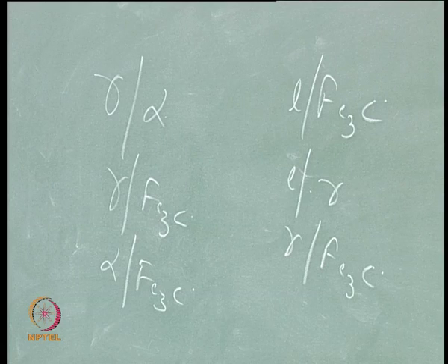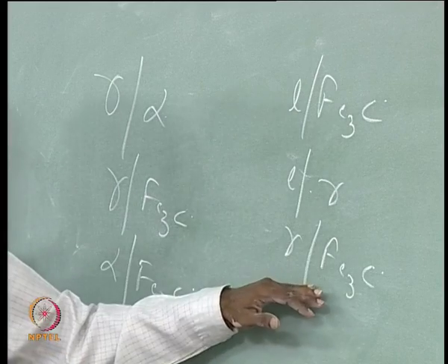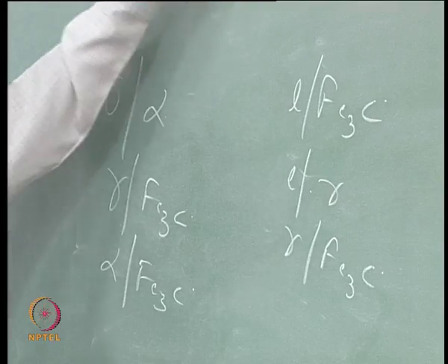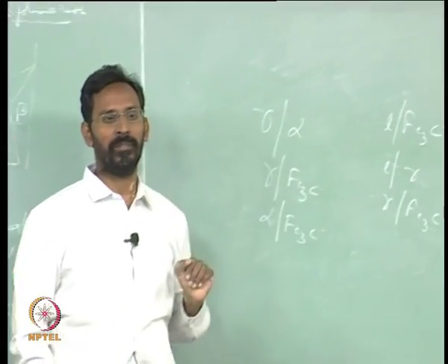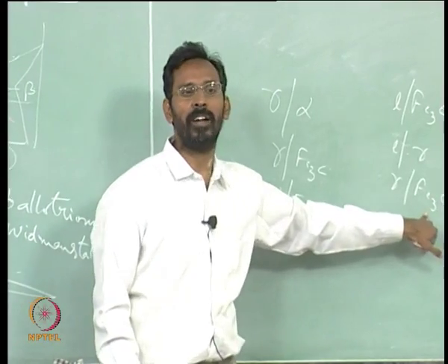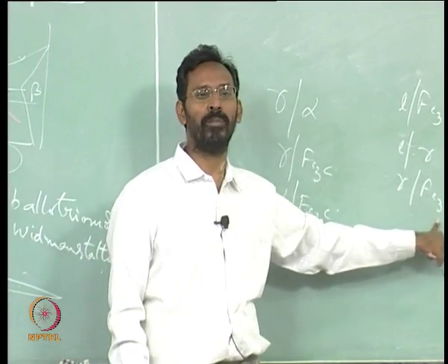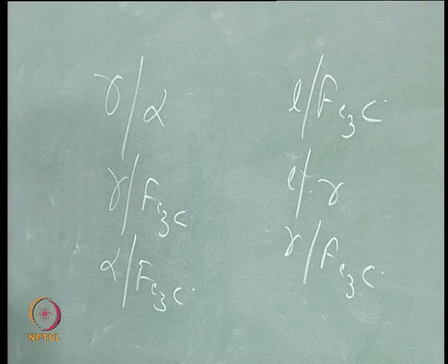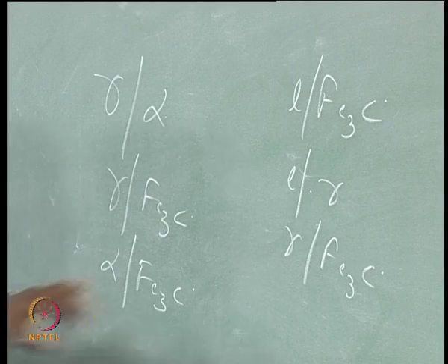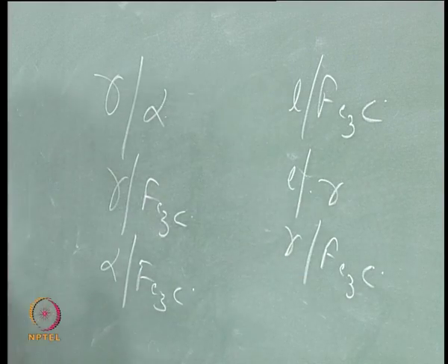In fact, you take a cubic, pull it, that is how you get a tetragonal structure. So, that is how you can see that there is a possibility of an alpha theta lamellar eutectic coming, whereas here you cannot get a lamellar eutectic because gamma and orthorhombic have no correlation, and compositions are also entirely different. As a result you will not see a possibility of a lamellar there.